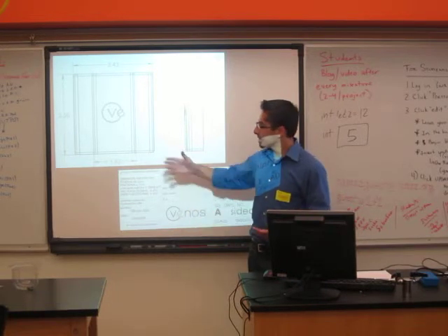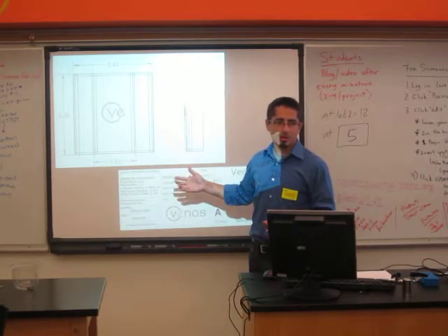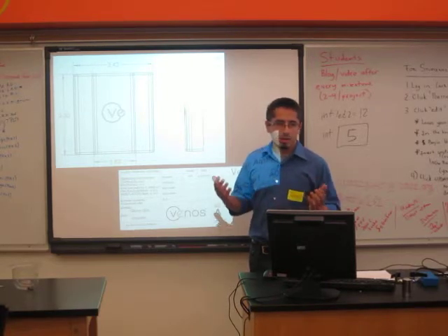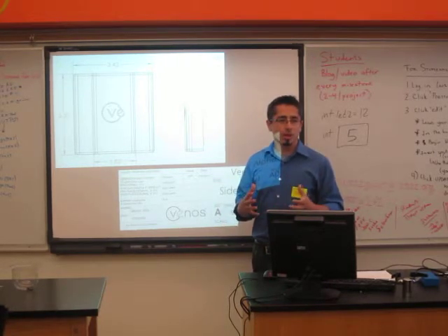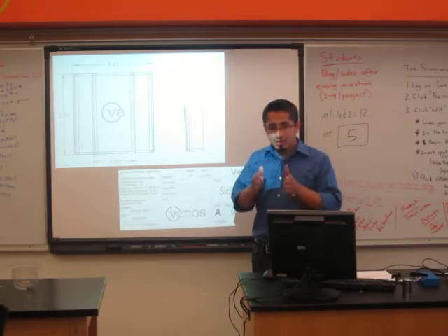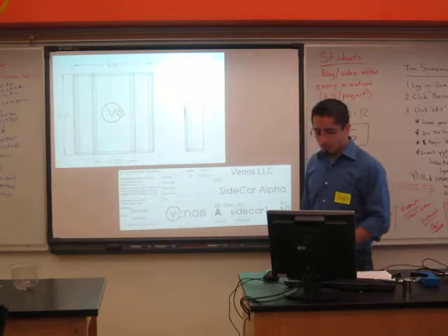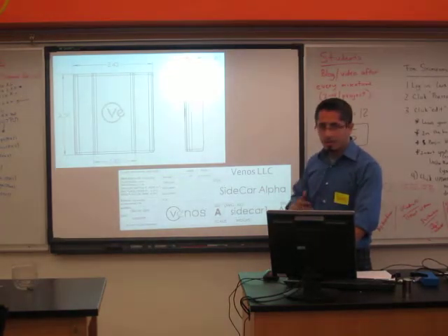So for you guys, keep your stuff simple and put a simple tolerance on there. Or say, I need it to be 3.0 inches plus or minus a 16th of an inch. It's not super precise. Or that needs to be super precise because that's fitting in between this one little spot. So those are a couple things you need to keep in mind. And feel free to ask us any time if you're like, does this look right?